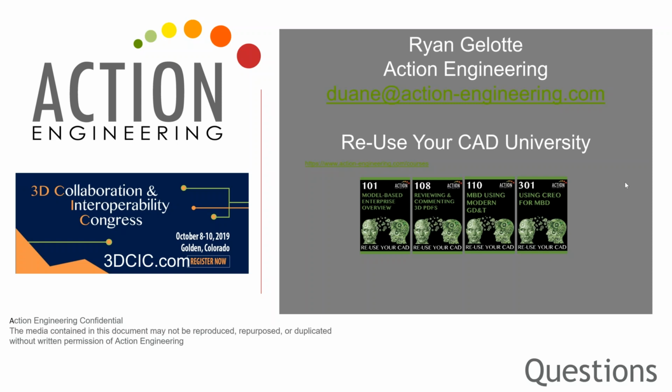Yes, I've had that question asked a few times. Right, Step 242 is an ISO standard for model-based definition, really targeted at consumption of model-based definition into manufacturing, and really not tied to any downstream specific discipline. QIF is a MBD derivative and interoperability framework, really targeted on quality systems, right? So it's not necessarily intended for manufacturing. So that's the main difference. QIF is really targeted on metrology and quality interoperability, and not anything beyond that.